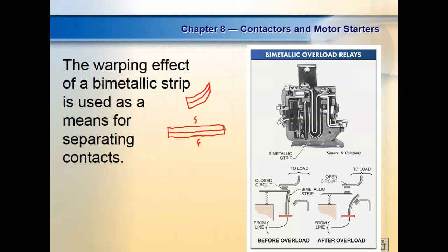And this is why most circuit breakers, if you're there when they pop, you can't reset them right away. You've got to let them cool down. Yeah, in houses. They do have all types of circuit breakers, by the way, but most of our houses use the ones with the bimetallic strip in there. So we can use that for overloads.